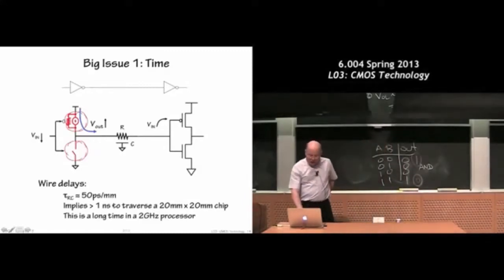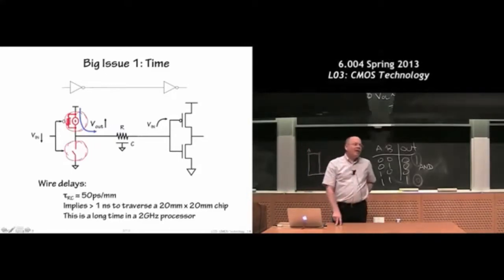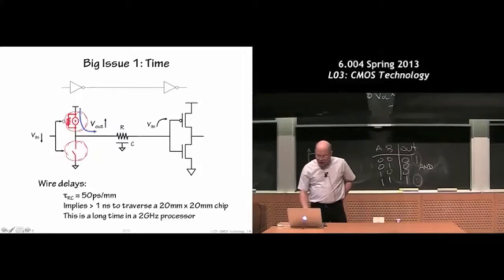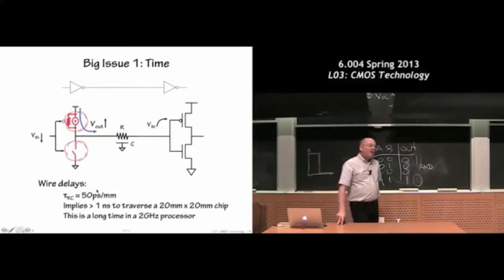And you can say, oh, this all seems pretty fast to me, Chris. Picoseconds, that seems fast. And the answer is yes, except you remember your chip is actually probably 20 millimeters across these days. And you're trying to design a set of logic and transmission wires that all operate within 1,000 picoseconds.